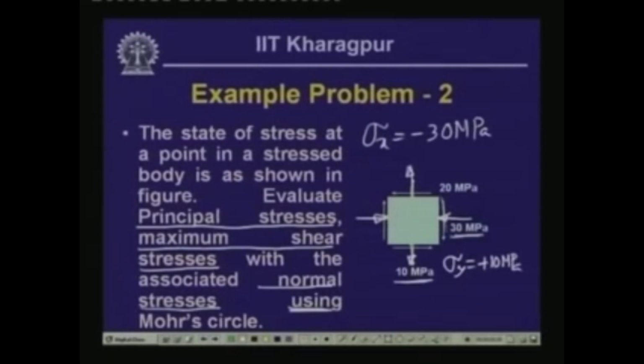Also, this particular shear along with the complementary shear on the other face is causing a rotation in the clockwise direction, which according to our sign convention is negative, because if you remember in the Mohr circle we said that the shearing stress causing anti-clockwise rotation is positive.